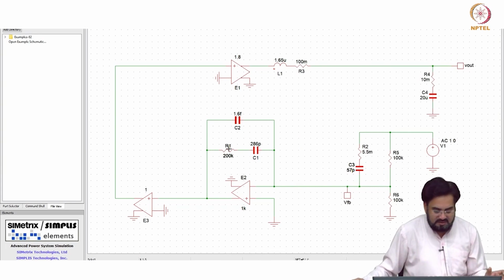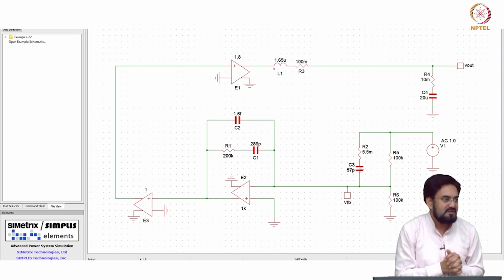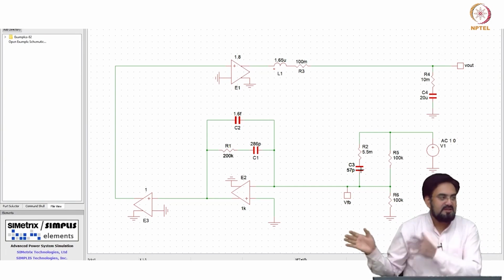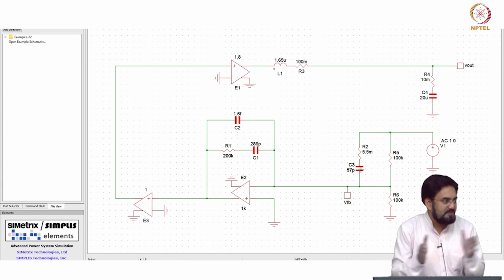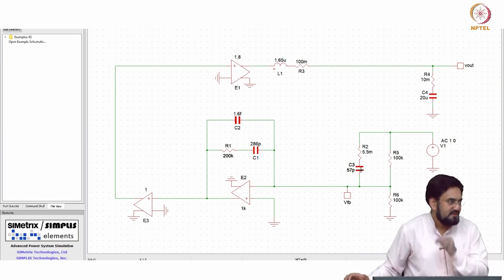And the same thing if you move the second 0 to a lower frequency, your phase will be boosted, because the phase contribution by this 0 at UGB will be more, as the separation between your UGB and that 0 is more. So that will add more phase at UGB.